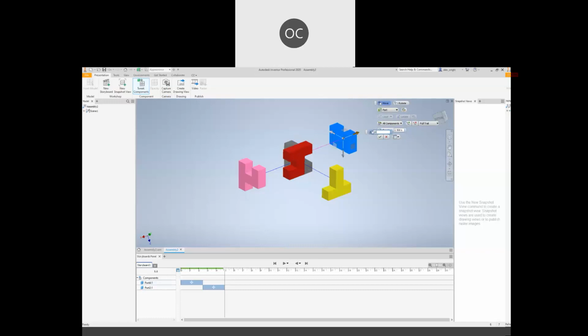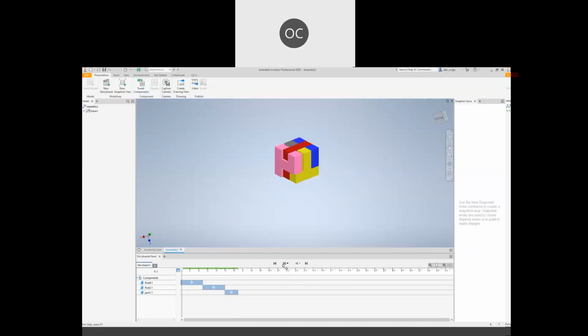One more thing that I would like to stress: you have the distance of 20 here, but maybe you will want to change the speed, the pace of the motion. It's available here, duration. In the default setting, it's 2.5 seconds. That means from the origin to the 20 distance that you set will take 2.5 seconds. If you want it to be faster, for example 1.5, you can edit it over here, then check it. You will see the blue one is relatively faster.